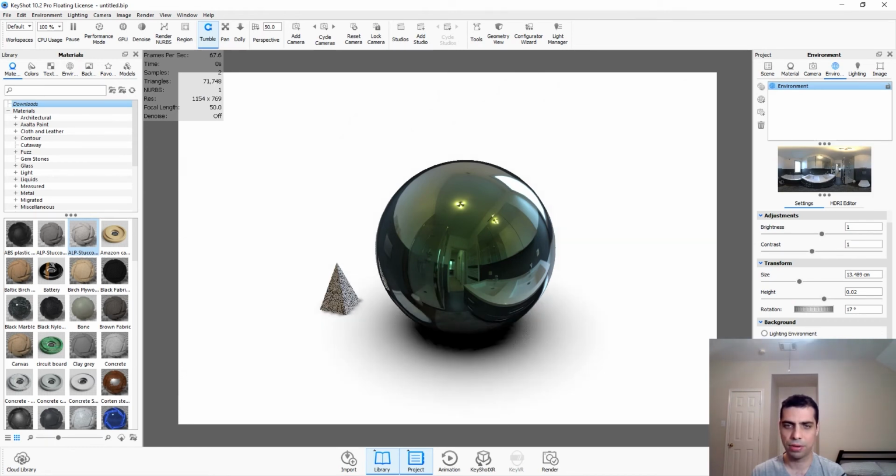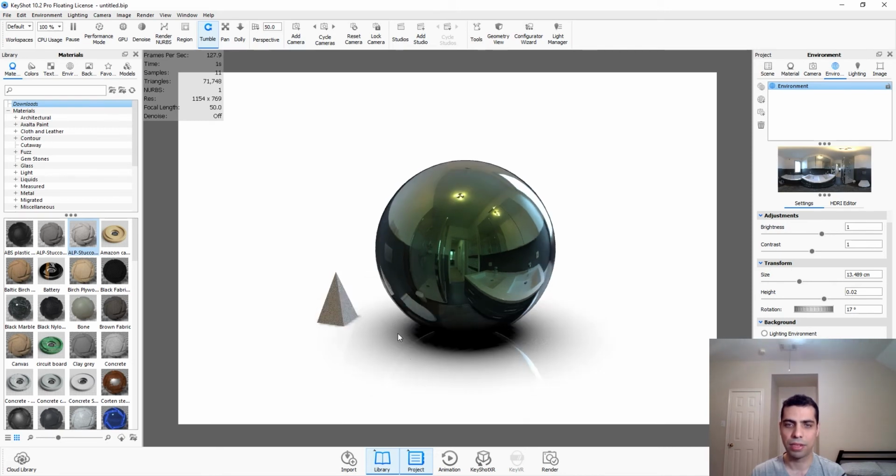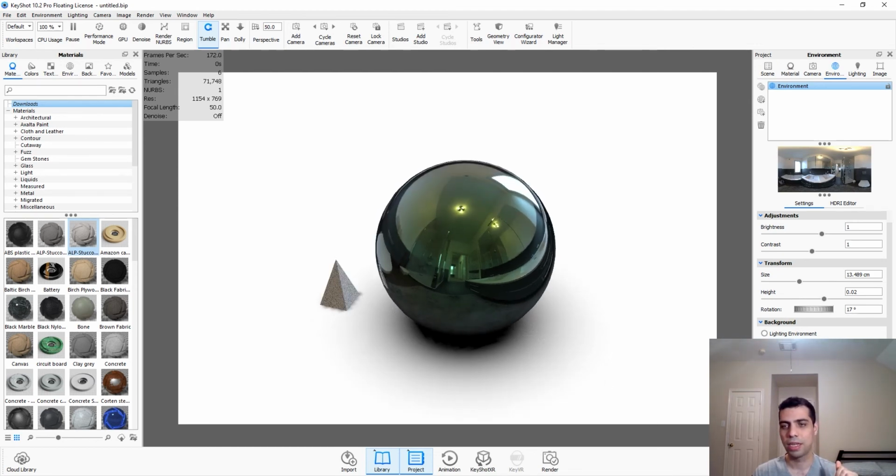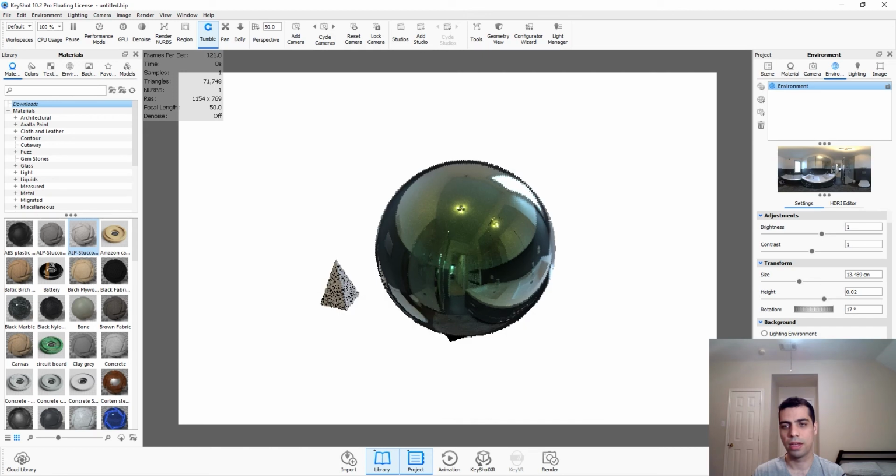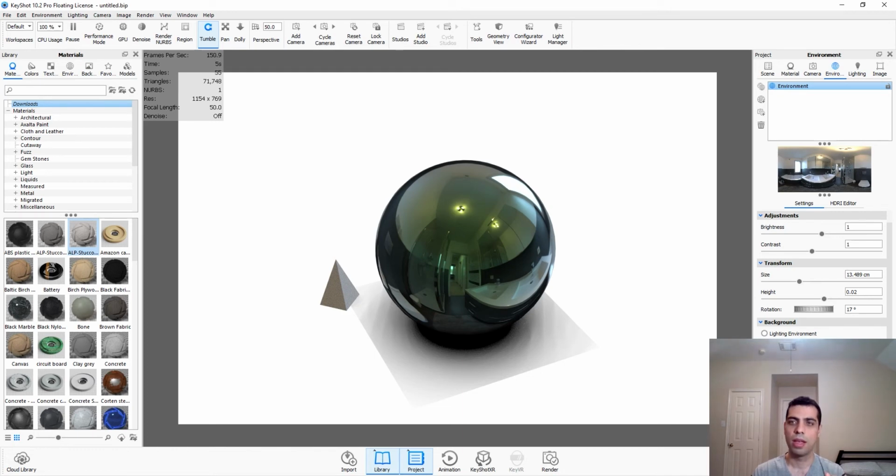Articulation, ground shadows, it adds ground shadows. Ground reflections, it would add a reflection on the ground. Though I don't want you guys to use the ground reflections, because you would have more options if you just add a ground plane. And flat ground, that would also change, as you can see, the lighting environment. I usually like to keep it flat if I want to be more fully realistic. And ground size, again, it changes the size of the ground. As you can see, this is our ground right now, 50.57 centimeters.